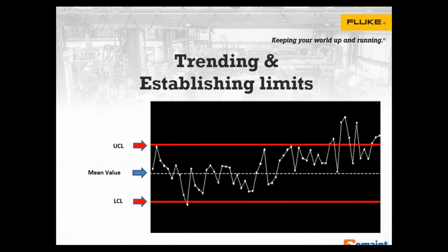What you're seeing right here is an example of an SPC, or statistical process control chart. This was introduced by a gentleman by the name of Deming after World War II. We're seeing data from a particular asset coming in, and there are tools out there that you can apply SPC to, which will automatically calculate a mean value and what we call upper and lower control limits. It's a great tool to apply mathematics to your data.